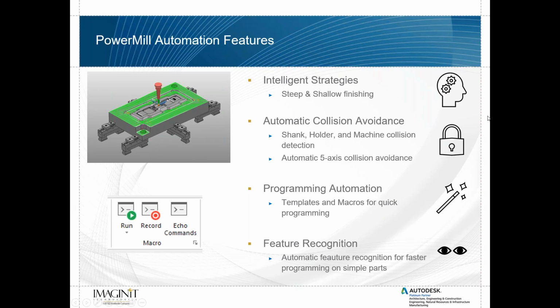So you can create these macros so that you can not only improve the speed that you're programming, but you can also improve consistency across the board. So if you have a team of 10 different programmers, if you're all using the same macros, things will be consistent and you'll be able to program more parts.